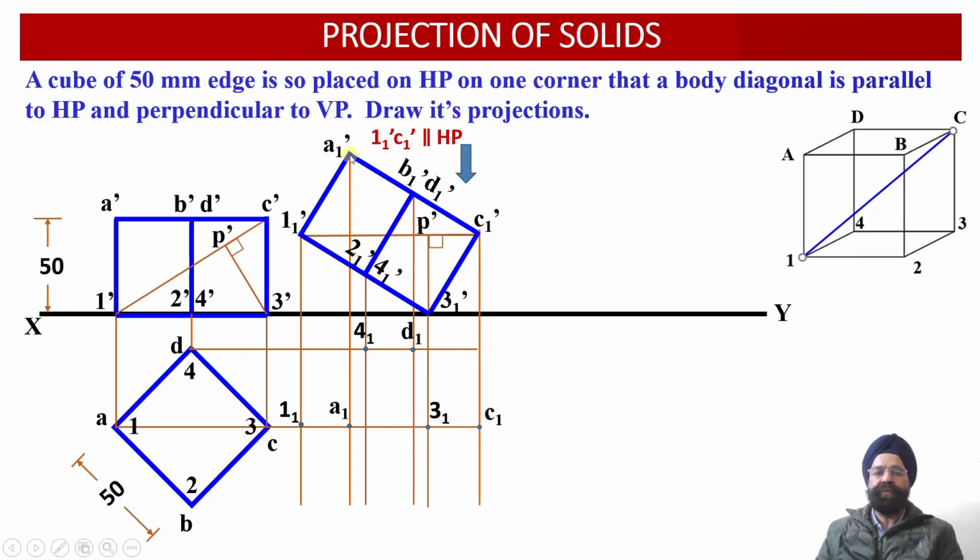view. So this is the vertical projector line emerging from A1 dash. So wherever it intersects with this horizontal line, it will provide us with the location of the point A1 in the top view. Similarly, this is point 3-1 dash. So once we draw the vertical projector line through 3-1 dash, wherever it intersects with this horizontal line which has been drawn through the point C, this point of intersection provides us with the location of the point 3-1 in the top view projection.